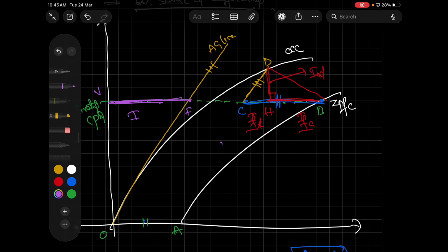This length I am considering as IFR. Previously, how was IFR measured? I used the EMF method. From that, I used the formula E0 equals the square root of (V phase cos phi plus IA RA) whole square plus (V phase sin phi plus IA XL) whole square. From the corresponding E0, I measured the IFR. Now for this ASA method, from the dotted rated phase voltage, wherever it intersects the air gap line, draw that, measure that length, and that length is considered as IFR. So we got IFR, IFL, and IFA here.